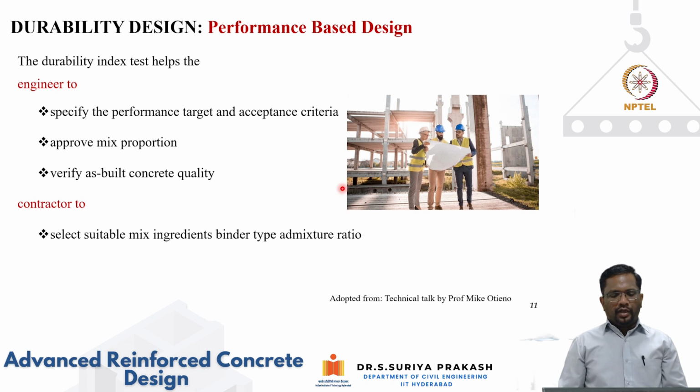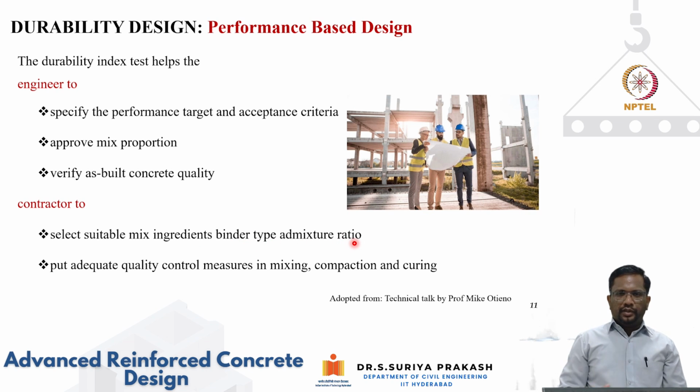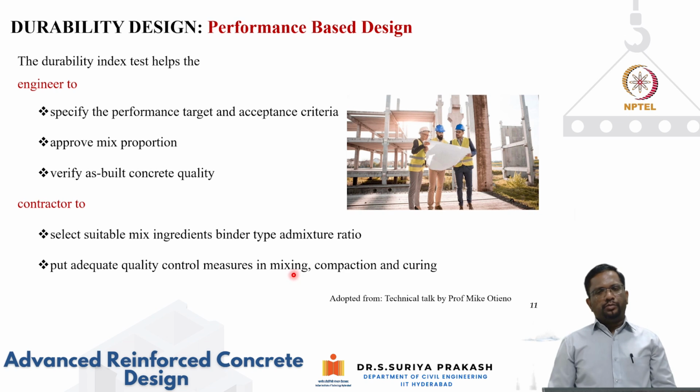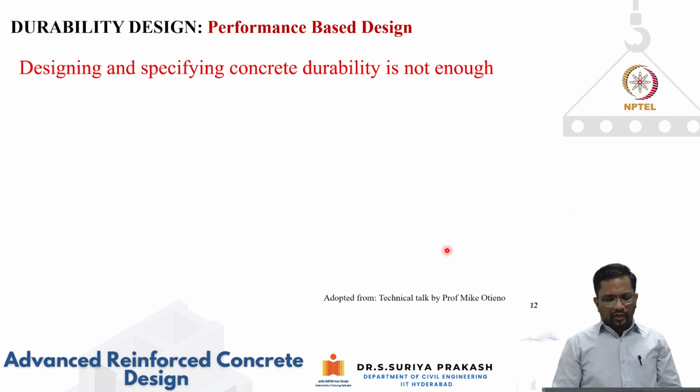But here, it gives complete freedom for the concrete mix designer to choose mix ingredients and binder type, admixture, and ratio to satisfy the durability requirements. And it also helps the contractor to put adequate quality control measures during mixing, compaction, and curing. And this is the big advantage with specifying the durability from a performance-based point of view.